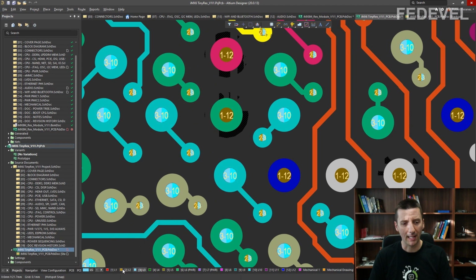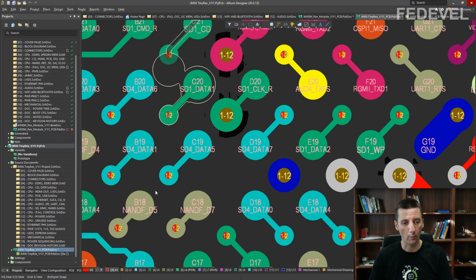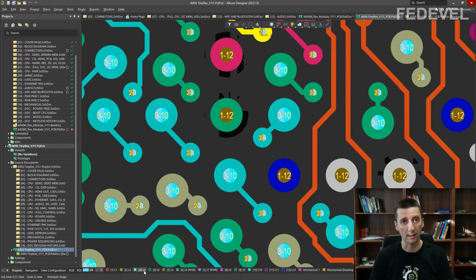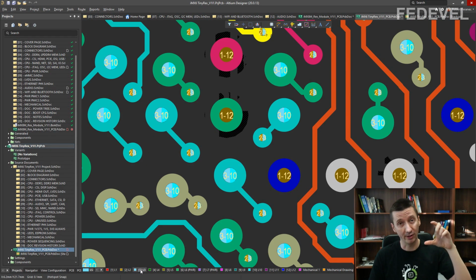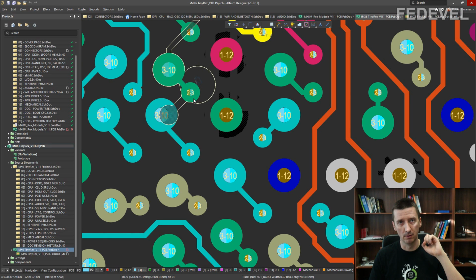Now, many people ask why we cannot just go from layer 1 to layer 3 with the microvia. Do you know? We were speaking about this. If you would like to go from layer 1 to layer 3, it will be a much longer distance. When we use a much longer distance, what is going to happen with our microvia? Do you know? We have to use a bigger hole.